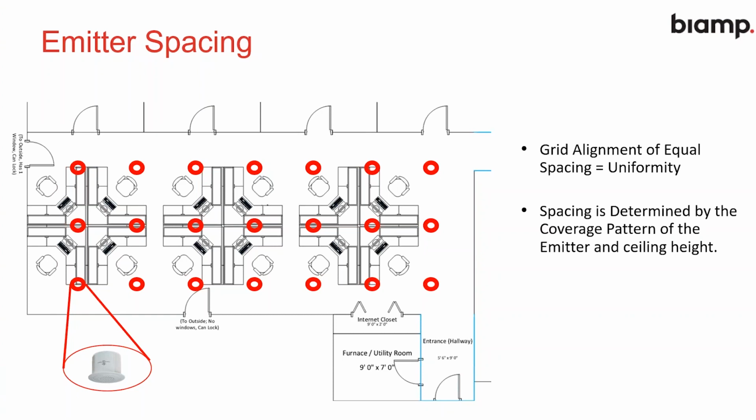So the ceiling height, as we've shown on the previous charts, is important. And with our sound masking systems in the direct field, we are aiming for plus or minus 1 dB uniform sound coverage. And that's the goal that we're aiming for. Some of that is assisted with the tuning, but the key to it is getting the design right.